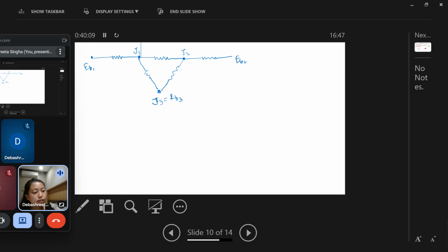And we have other resistances also. So these are known as the surface resistances. Surface resistances are there because the surface is radiating, so they have some surface resistance, and there are also some space resistances which are due to the view factor.